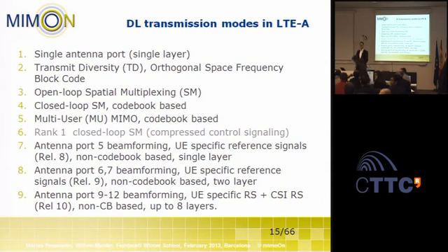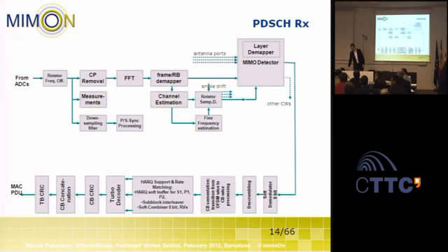Why are there two CRCs? These two CRCs are there so you don't need to wait for a complete transport block to arrive. You can also make decisions whether there is a correct or false reception based on these short code blocks. So that allows you to save time, and you can immediately initiate a retransmission.